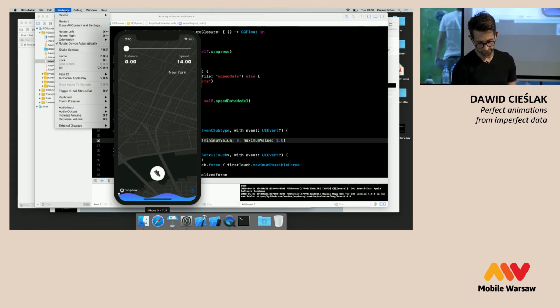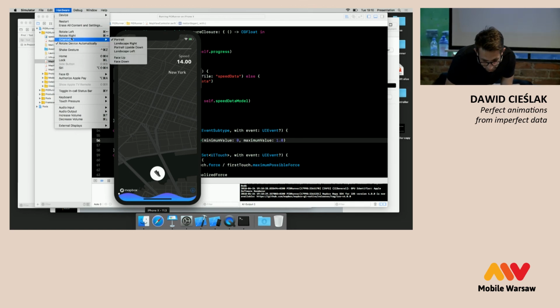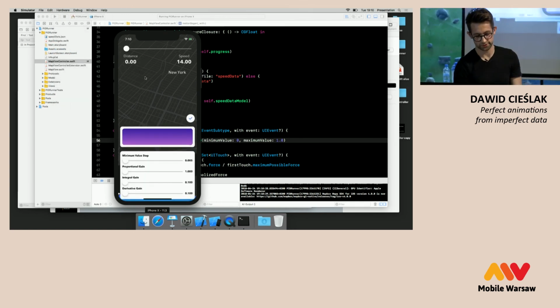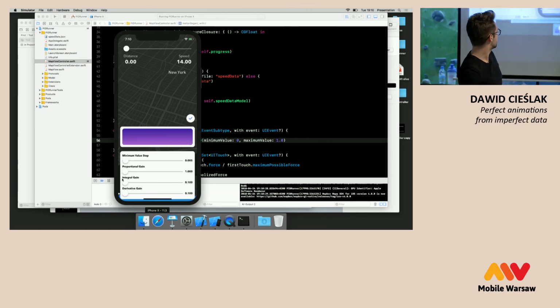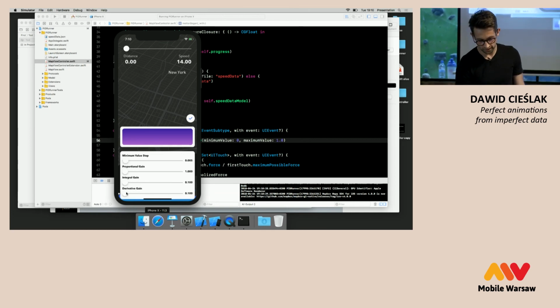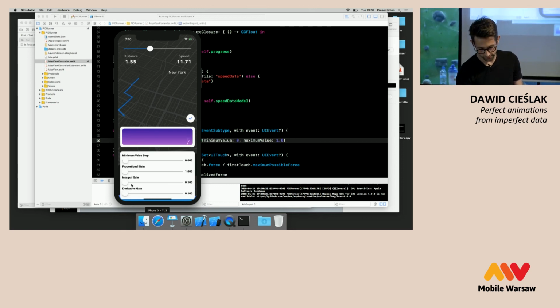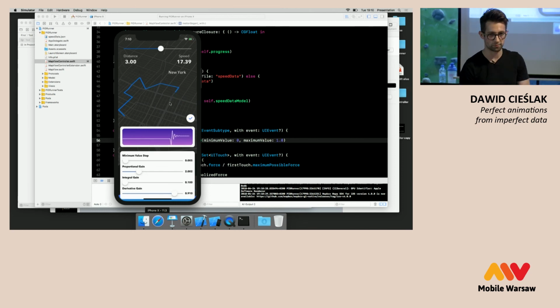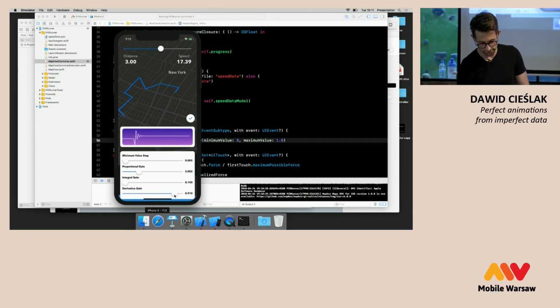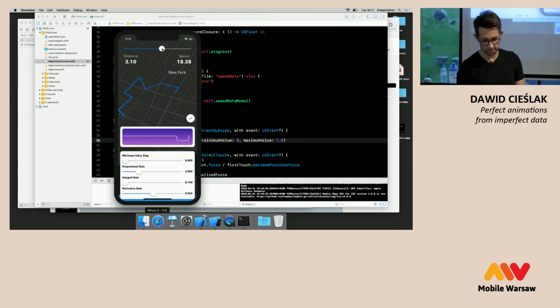And now, when I trigger shake gesture, I have an extra view that kind of helps me to control all these values of PID Controller. So I can just easily change something and see on graph how it works. So you can see that this function might have too big overpitch for your solution, and easy you can change the function, change the factor, and now it looks a bit better. We still can trim and find something that works for us.